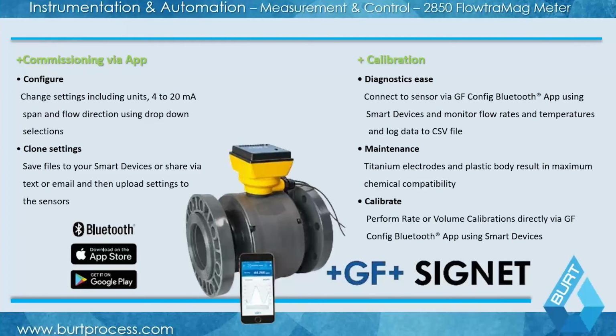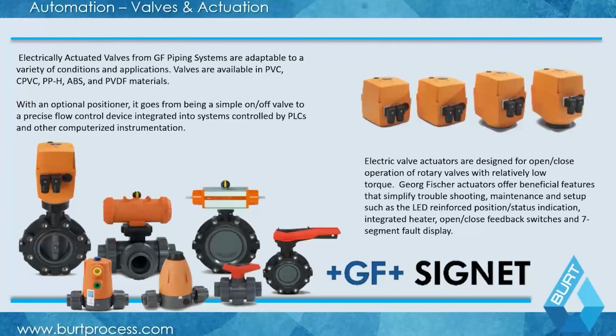As a result of that, usually at the end of the system, you'll have some form of effluent monitoring. This effluent monitoring typically includes pH as well as flow meters, like the one shown on the screen, that allow you to, one, track the flow being discharged from your system, as well as allow you to record that flow in comparison to the pH to make sure that your pH system is working within the verification steps that are allowed by your local municipality.